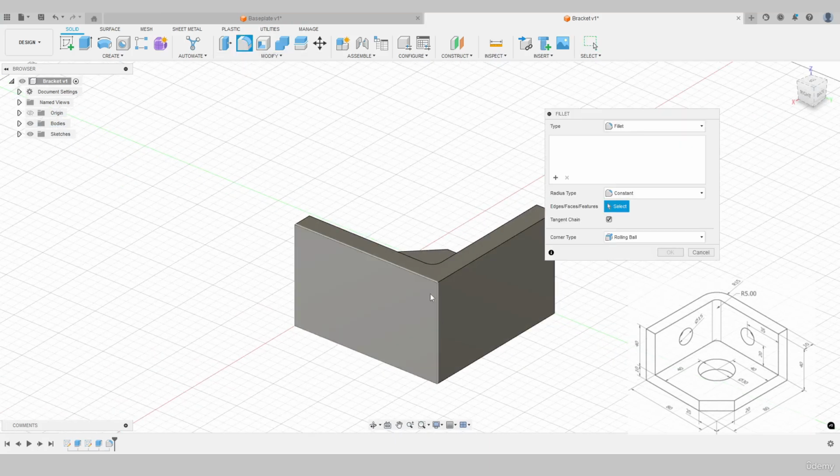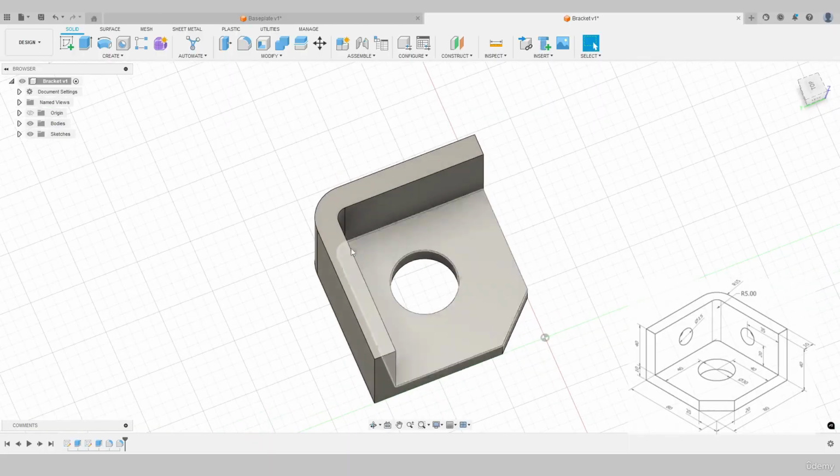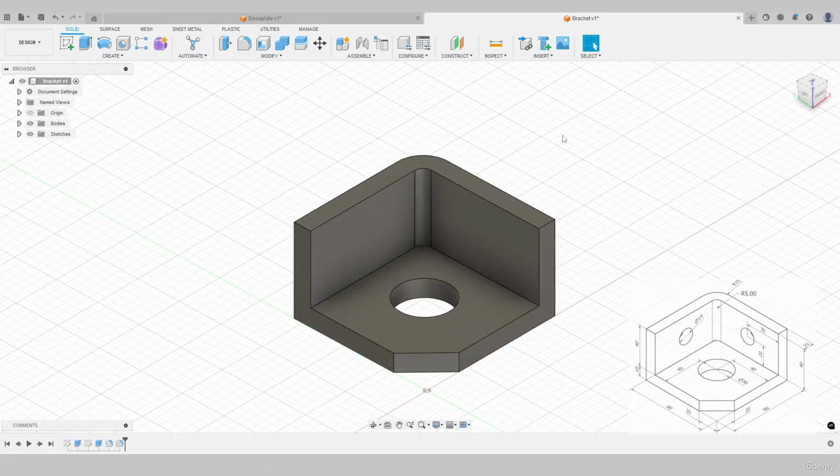We've also got the fillet on the exterior here. So let's choose the fillet tool again. We'll select this edge here. And this dimension is 15 millimeters as per the drawing. Press OK. It's looking nice. And we've got that uniform thickness running along the back wall. We've just got two features to add here. One is the hole on this wall and the other on this wall here.